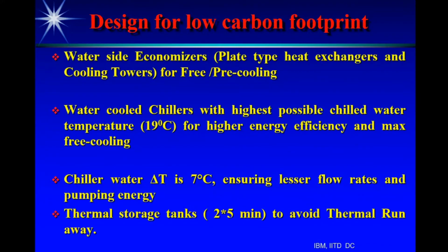So the idea here is, in this particular design, we have gone for free cooling and pre-cooling, which means during the winter months, when the ambients are low, a server room would still require cooling because the servers are generating heat. So we are just capturing that heat and throwing it into the ambient. That is what is called free cooling. Similarly, when the ambients are lower, maybe we are not able to cater to all the cooling, but if we are able to reject some of the heat to the surroundings, then the load on the refrigeration air conditioning system will go down. These concepts are being taken into account in the design of our data center.